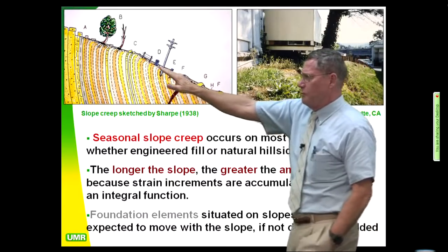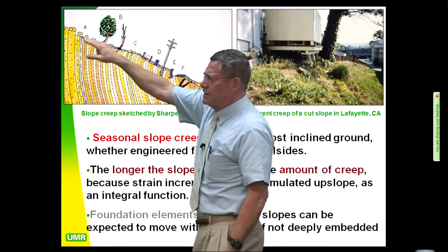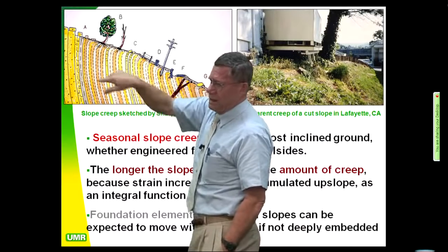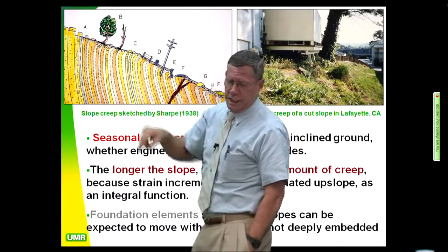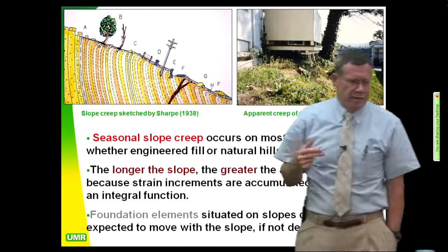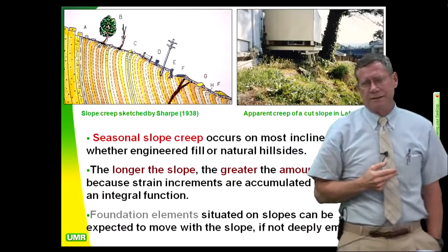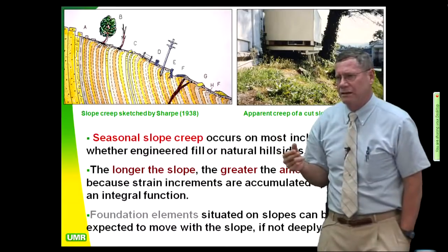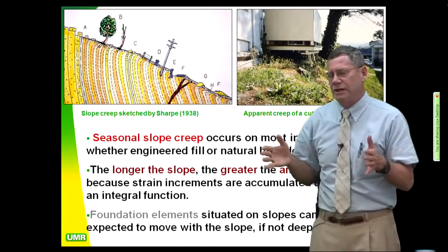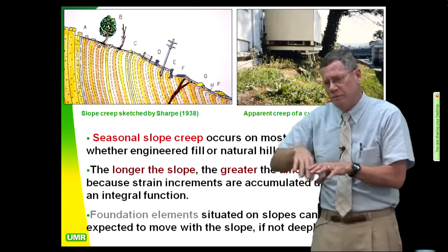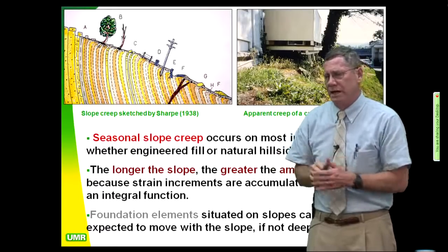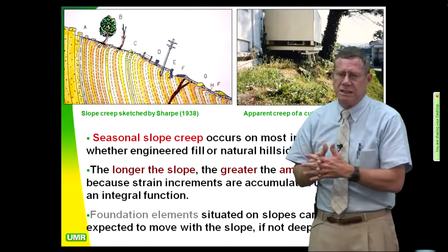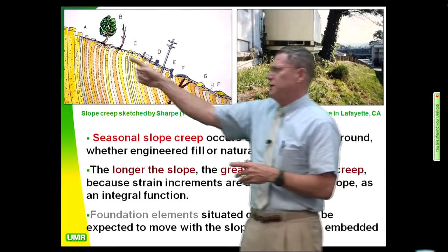And obviously if you have a point source of moisture, like a leaky fire hydrant or a leaky elbow on a water line or something, that is really going to exacerbate the situation. And you won't pick those things up with sonic velocity log testing. That only picks up the big things. You won't pick up leaks that are just weeping, don't make any noise, like you get at elbows and at T's. So when you're up in the areas like this, that's a big problem in Honolulu.